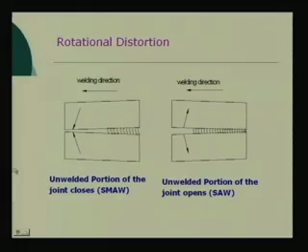In slower speed, what will happen? The heat flow in the leading edge of the welding will be substantial. So, contractional forces will work in the front also, and we will try to close it. So, that is how these are the problems.